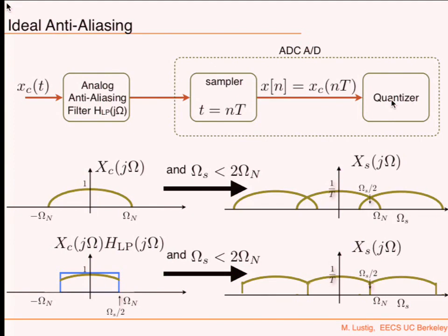Okay? All right, so in the model there, we have some spectrum, which is band limited. If we sample it at a rate which is lower than twice the highest frequency, then you're going to get aliasing. For the lecture today, we're going to define omega sub N to be the Nyquist frequency.